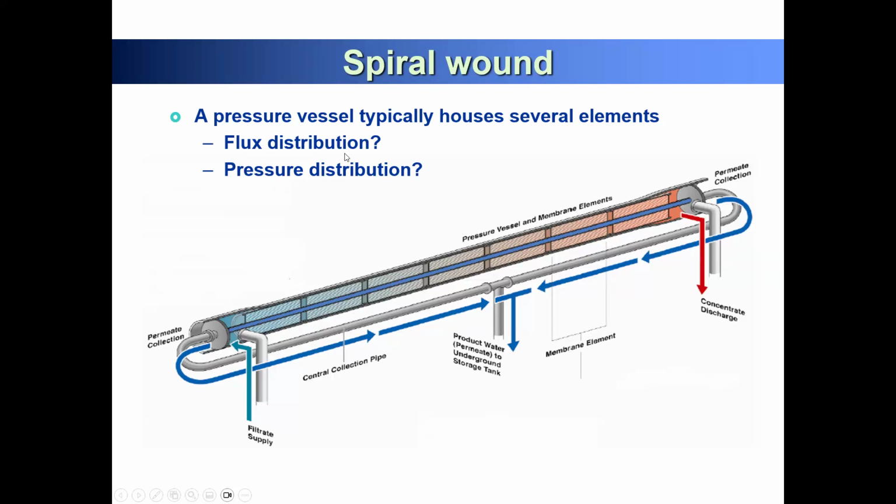So we have a flux distribution. You have a higher osmotic pressure increase, and then you have a low water flux. Pressure will be lost. In the initial stage, for example, seawater goes to here, and then you keep concentrating your feed water, and pressure keeps losing and losing, so that pressure loss will be there at the end of your pressure vessel.